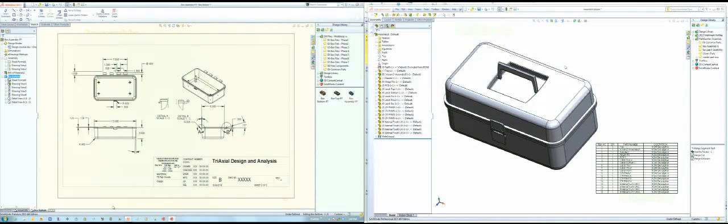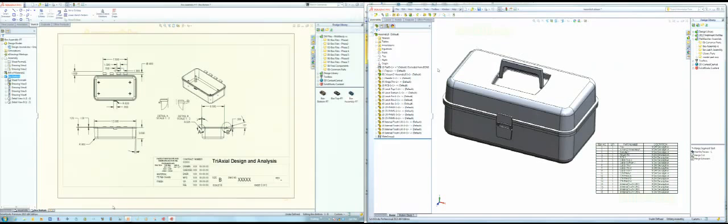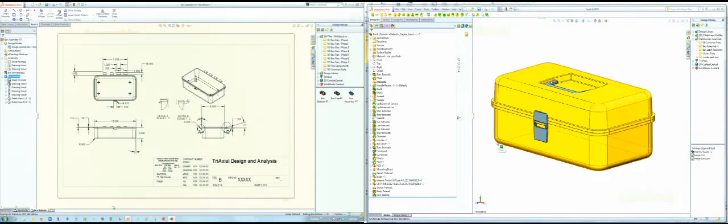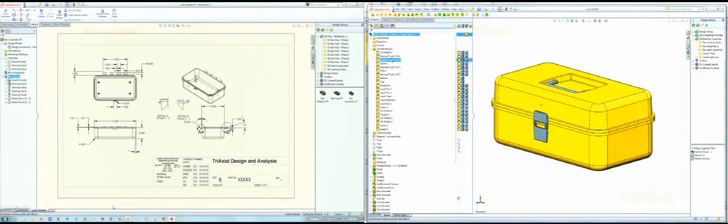Okay, this is our assembly that I just created. The way we created that is we went out to the part, and for the very last feature, now when you say save bodies, we come up here to the solid bodies. The first thing you need to do is rename all your bodies so they're the same as you want the file names to be. This is the easiest way to do it. Go through there first and rename them all to whatever you want the file name to be. And that'll stick. That won't disappear the next time you work on the body.